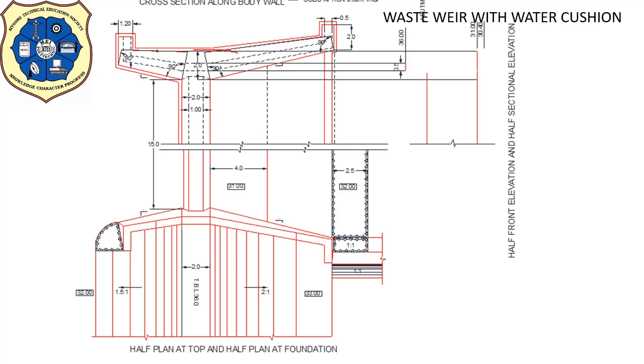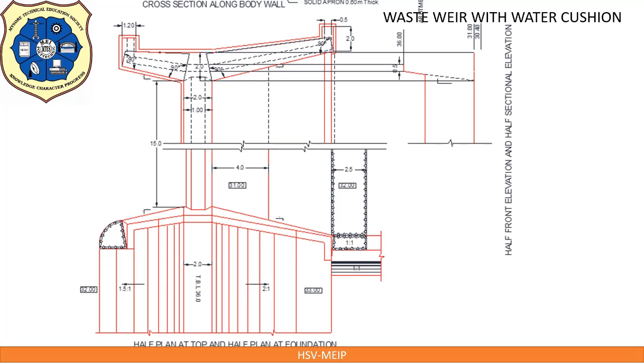This is the abutment bottom width. Then the top width of the abutment. This is the top width of the abutment. Top width of the abutment should be shown at the 36.00. Bottom width at the 31.00. Project these lines. Join top width with bottom width.